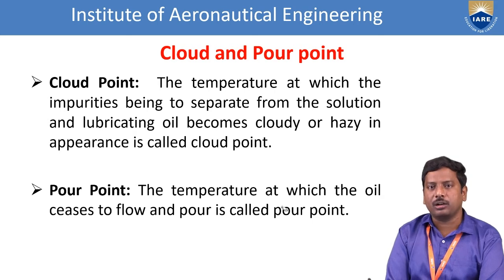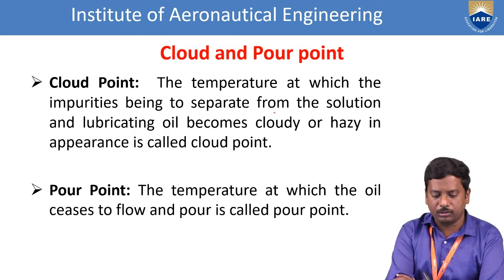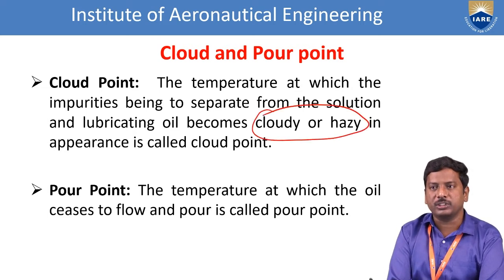Cloudy means the oil should not be clear. Why should it not be clear? Because of the impurities present in the lubricating oil. Such a position is nothing but a cloudy or hazy position. That means the temperature at which the impurities begin to separate from the solution and the lubricating oil becomes cloudy or hazy, that appearance is called the cloud point.